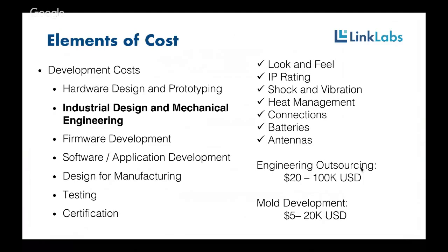The IP rating or the protection rating, how water resistant, submersible, spray proof, temperature, shock, vibe, all of these things need to be considered. Some of these systems, especially the higher power radios like cellular, even LoRa, they can generate a lot of heat, and that heat needs to be dissipated or at least thought about in the design of the enclosure.